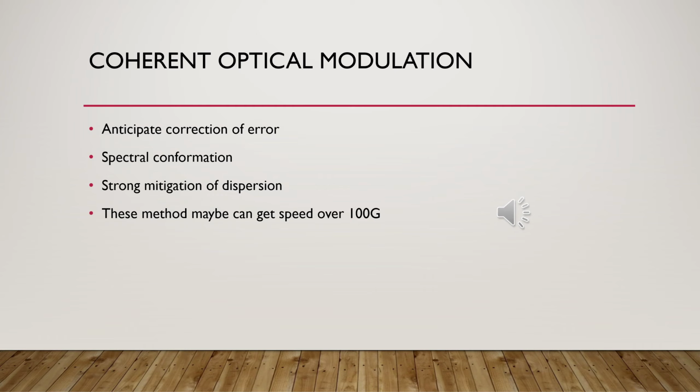Actually, the other thing is spectral shaping. This gives you more capacity to reconfigure the reconfigurable optical add drop multiplexer, called ROADM, and this makes the spectral super channel more efficient and gives more connection flexibility. One of the strongest things about the current optical modulation is that it is easy to program. This means it can adapt to very different technologies, networks and applications using the same board. As I said in the last slide, this is our digital processing of the data, and with some changes in the code, you can do very different applications.